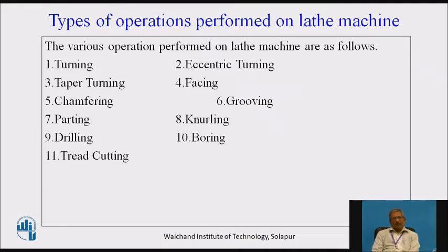Boring: after drilling, if you want to enlarge the hole, then you can carry out boring. Boring is nothing but removing the internal surface of the drilled hole. So it is also a turning, but turning inside the hole is called boring. And thread cutting is the generation of a threaded surface either inside the bored surface or outside the turned surface. It is just like a nut and bolt arrangement, you can say. So that type of threading can be done.